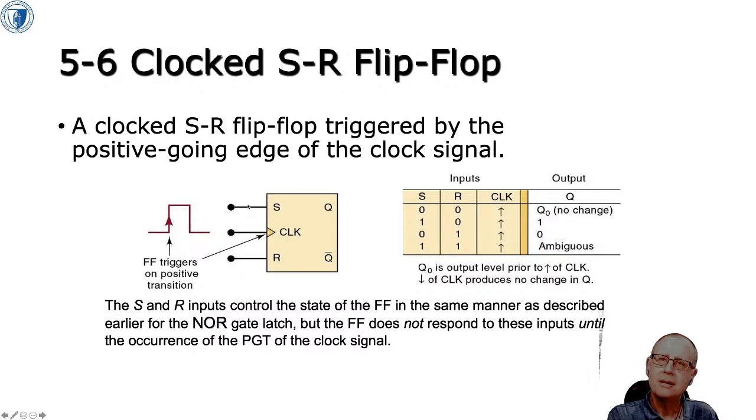So the other thing to note is all three of these inputs, the clock, which I talked about before, but also the S and the R, are active high. That's why set is high, does the set, and reset is high, does the reset. Okay? Everybody okay with that?